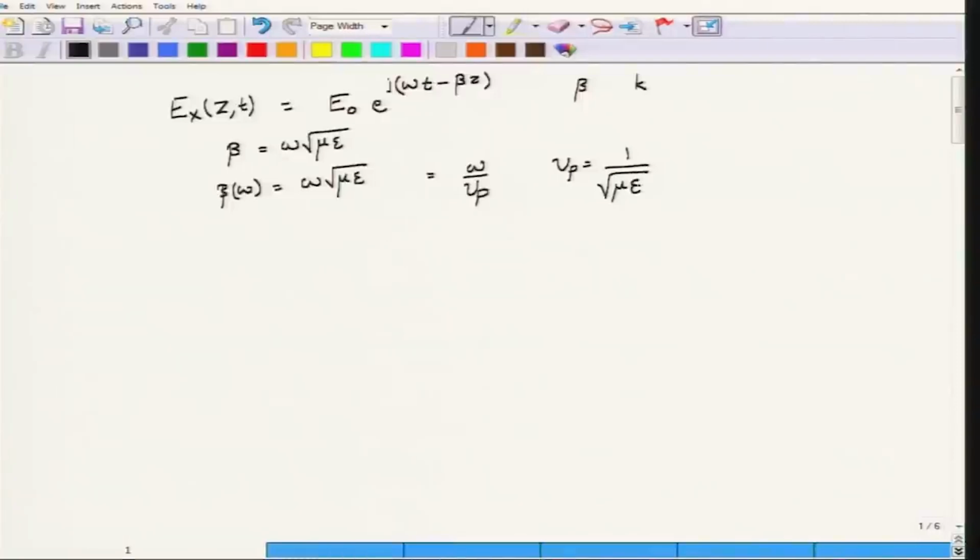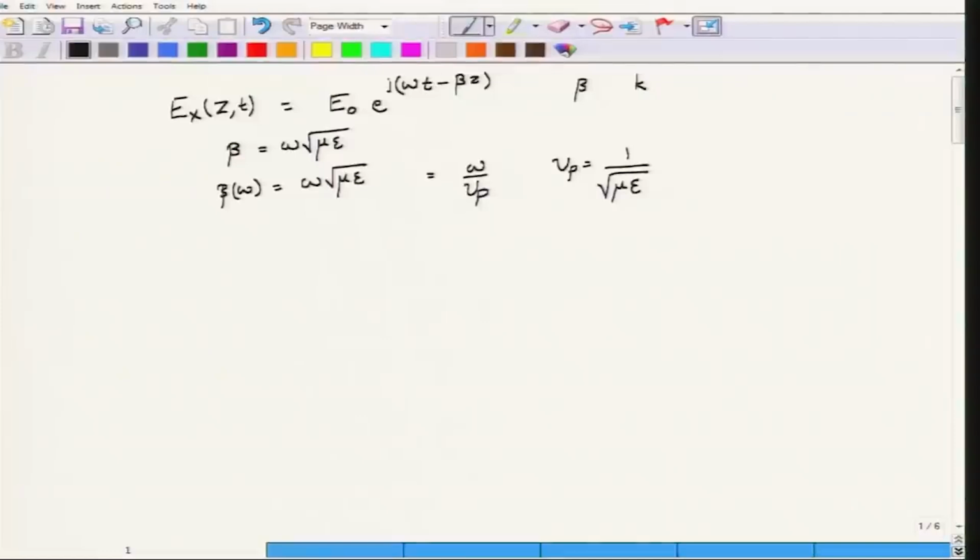It can be applicable for a homogeneous dielectric medium which is assumed to be unbounded, or it could be applied for free space wherein you will substitute epsilon equal to epsilon 0. Now, this is the complex notation for the wave, as you might remember. So, this would be the cosine solution that I have. Of course, this solution keeps propagating all the way from minus infinity to plus infinity.